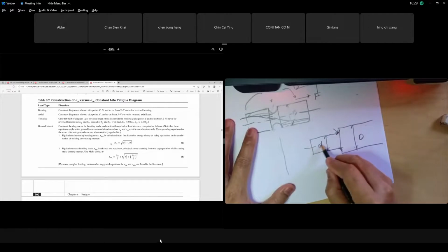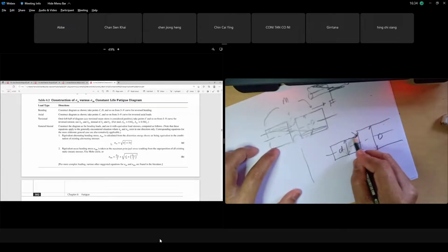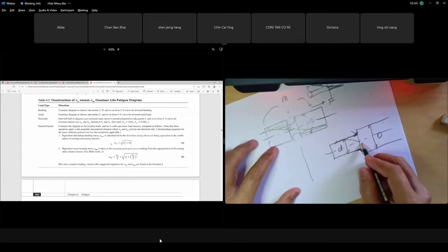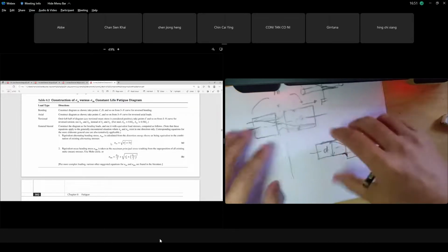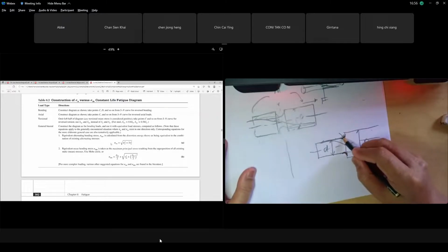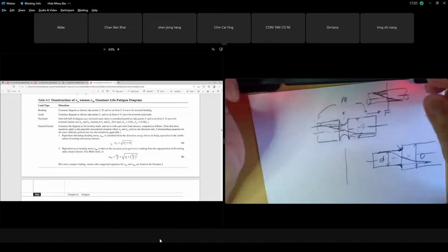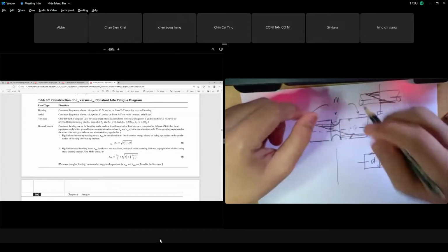At this shoulder, this is your neutral axis. If you apply axial stress and also bending stress, the stress distribution at the shoulder too, because we have a curve, is larger. It becomes more distorted. Let's say for bending stress, this is the compression side. But at the notch it becomes more distorted, larger than the plain smaller diameter, because we have steps in it. All these curves, like this notch, this groove, cause what we call stress concentration at that notch. So that is your weakest point.